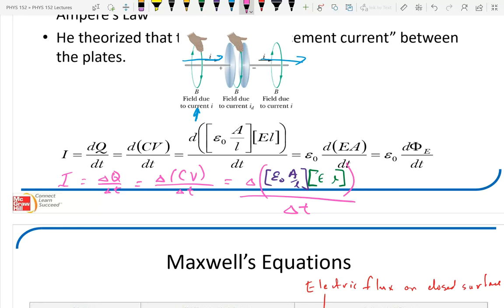And then we have, well, what's constant? The permittivity of free space is constant. So the epsilon 0 is constant. The area of my capacitor plates is constant, assuming I just have a simple capacitor. The separation between the plates is constant. And so this simplifies to bringing out all the constants. Notice the L over L cancels.